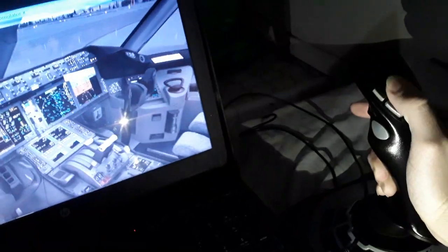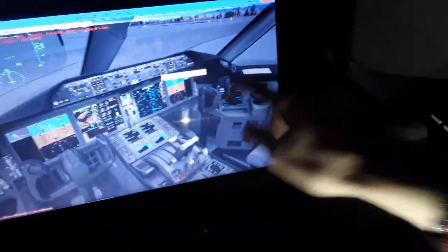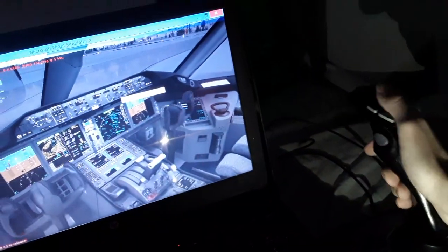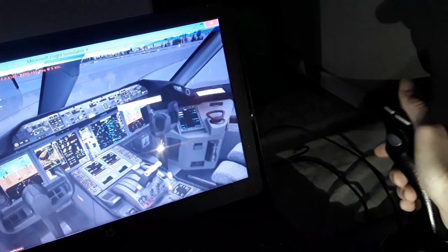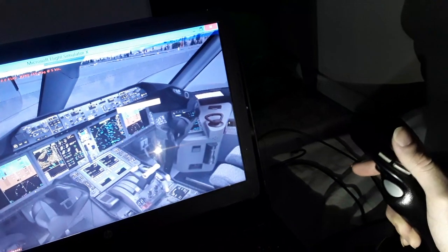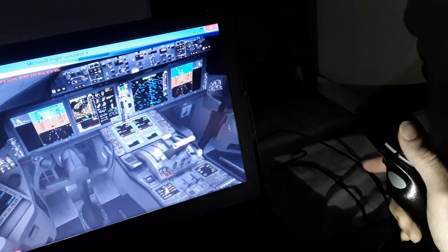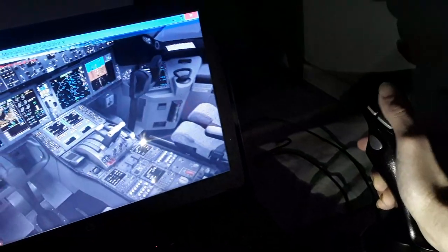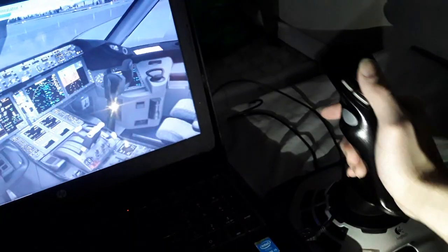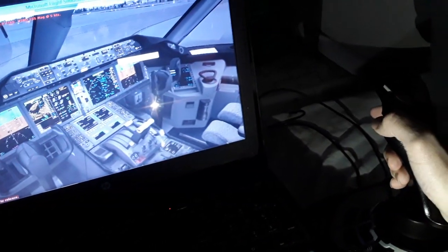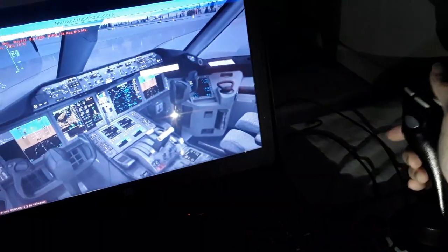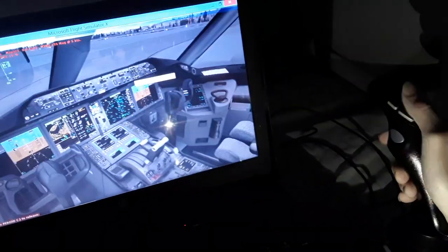You can see both sides move together, the left and the right, the captain and the first officer. Unless we have a failure, all the flight controls are interconnected: the yoke, the control wheel and the rudder pedals. Also, they're not like in the Airbus. You have the side stick priority button for the captain or the first officer. You can use either side at the time you need.